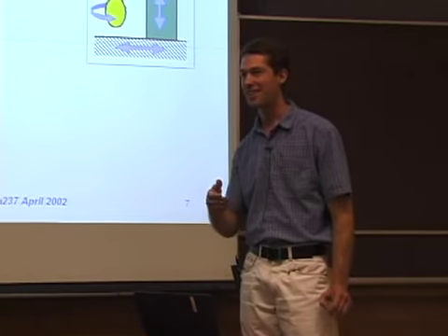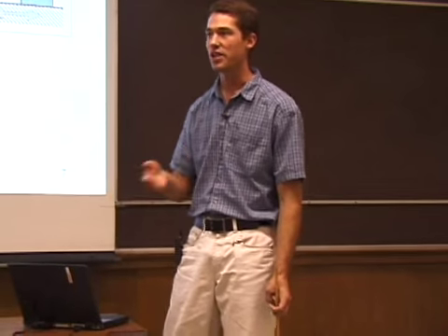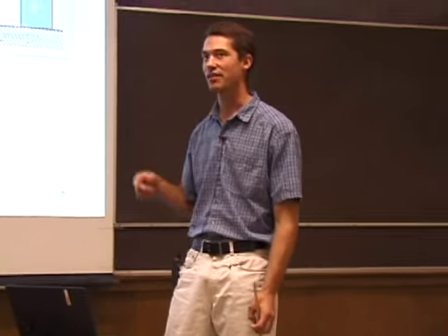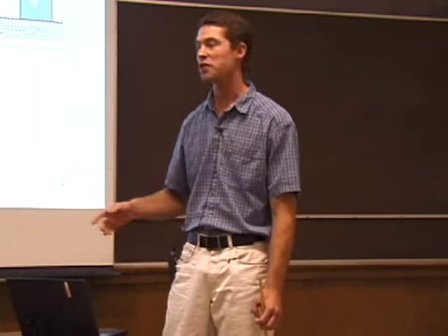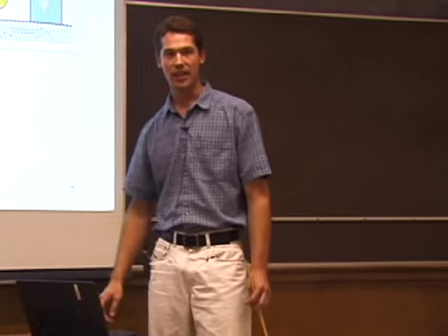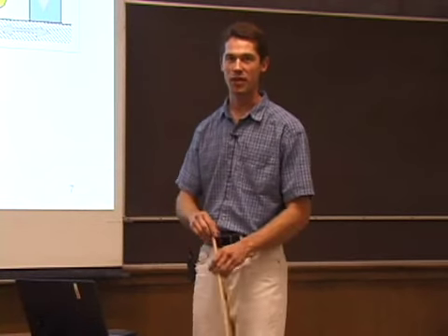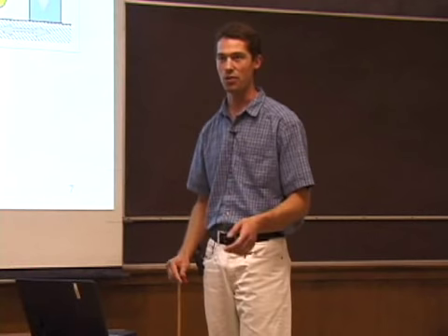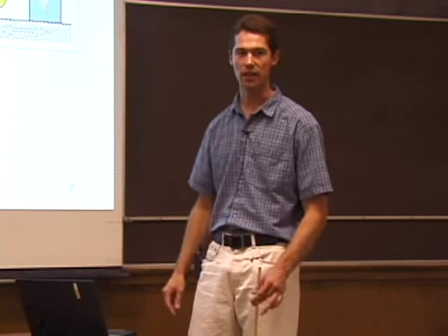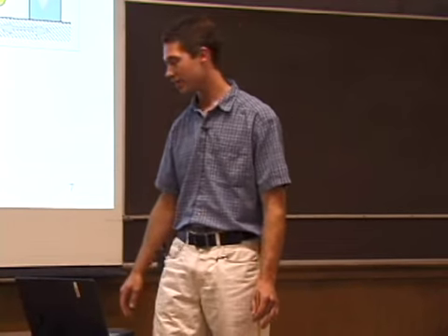Despite the fact that I say very close, they're still not within the dynamic range of the actuators, so we don't hope to hit them. That is, you hit the nonlinear effect of the actuators running out of range before you hit the earthquake stops. The actuator range is like a couple of microns, right? Something like that, a few. The question was, what is the actuator range? And the answer is of order a few microns, I think tens of, but like that. Whereas these things are millimeter type range.